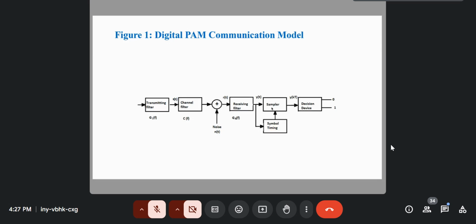So you want to sample in the middle of the pulse to find out what the voltage is. And normally we are not testing just at the middle of the pulse. We are collecting the power, the energy over the interval, so that depending on the energy you get, you can use energy because there's a time factor. Then you decide whether this was a 0 or 1.